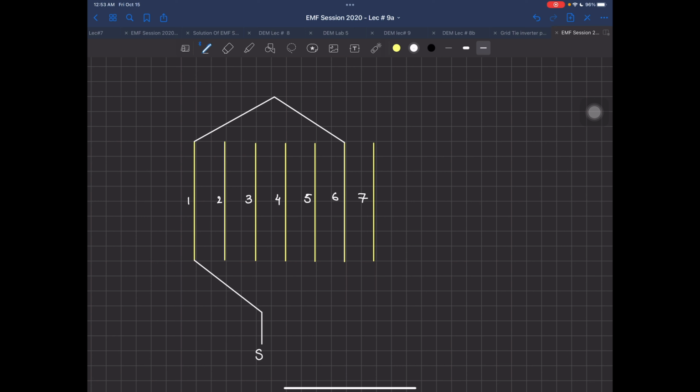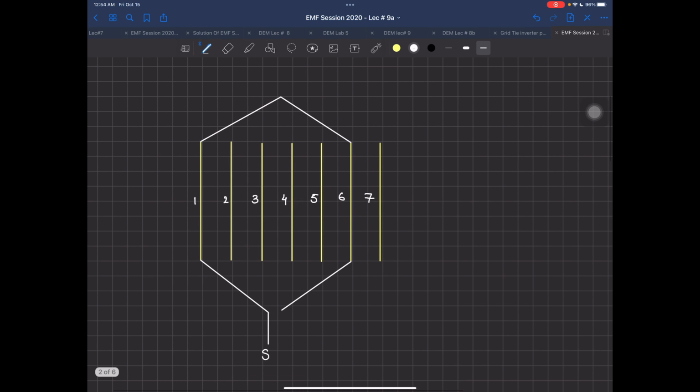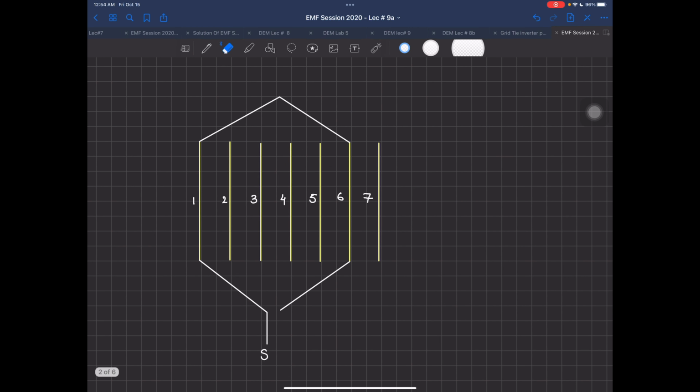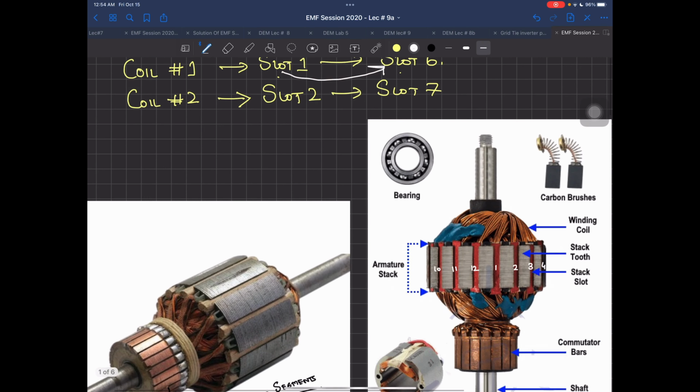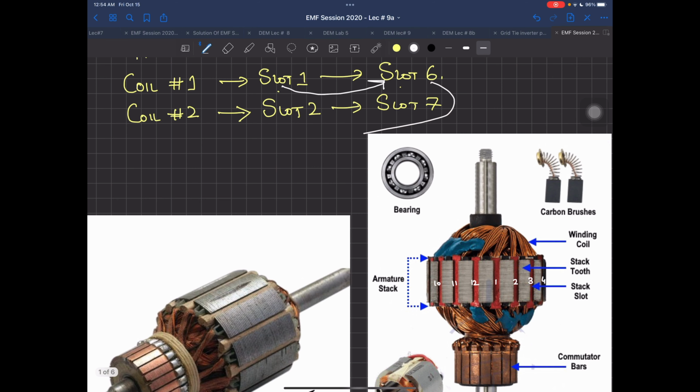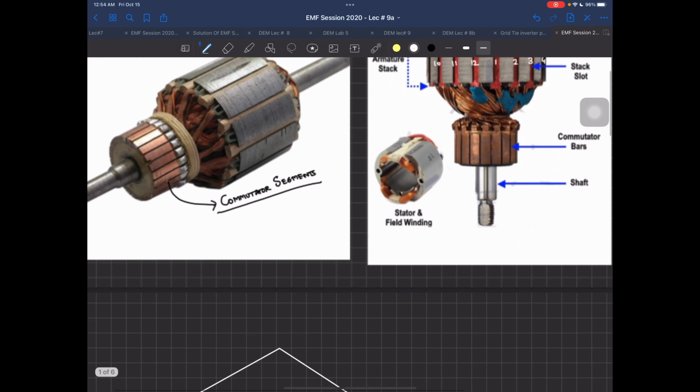So your coil completed from 1 to 6, and then it will bring back the wire from here, and then you will again do many turns. But I'm not going to show those turns, for an obvious reason, because that will make the diagram cluttered. So from 1 to 6, this is one coil shown. Now from 6, as I just told you, I will go back to my slot number 2 and then start another coil.